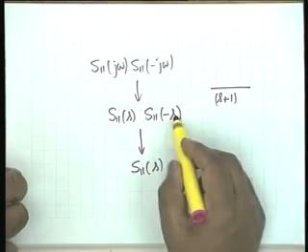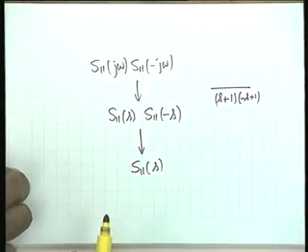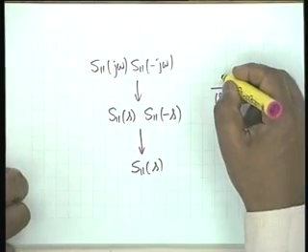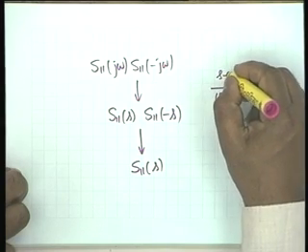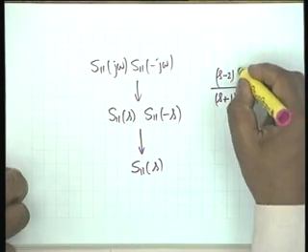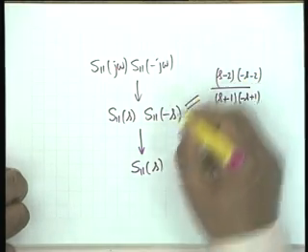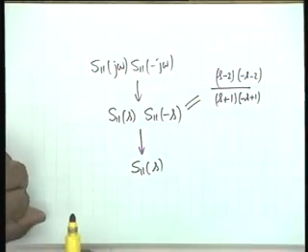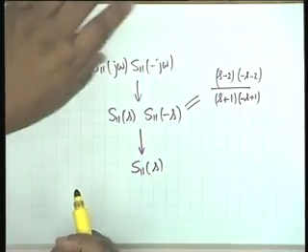So, if this quantity has a factor like this, then minus S plus 1 should also be a factor. Similarly, in the numerator, suppose you have a factor of S minus 2, then you must have a factor of minus S minus 2 also. So, S11 of S and S11 of minus S can be factorized into the roots of the numerator and roots of the denominator. Okay.